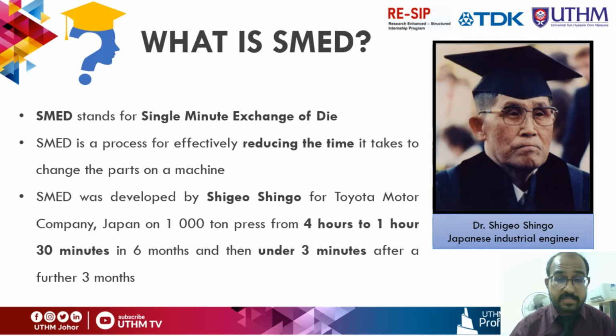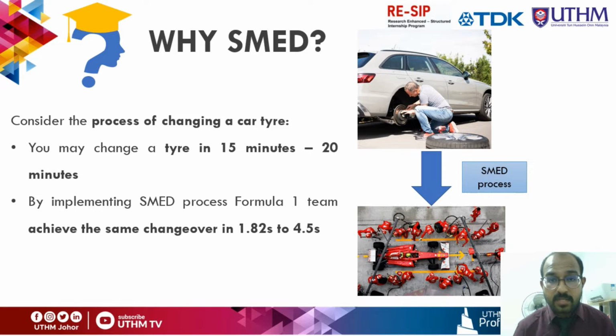Moreover, SMED was created and developed by Dr. Shigeo Shingo, a Japanese industrial engineer, who first implemented the SMED method on a 1,000-ton press at Toyota Motor Company, where he successfully reduced the setup time of the press from 4 hours to 1 hour 30 minutes in just 6 months, and then to under 3 minutes after a further 3 months. So in a nutshell, I can conclude that SMED is a proven tool to reduce the setup time of a machine.